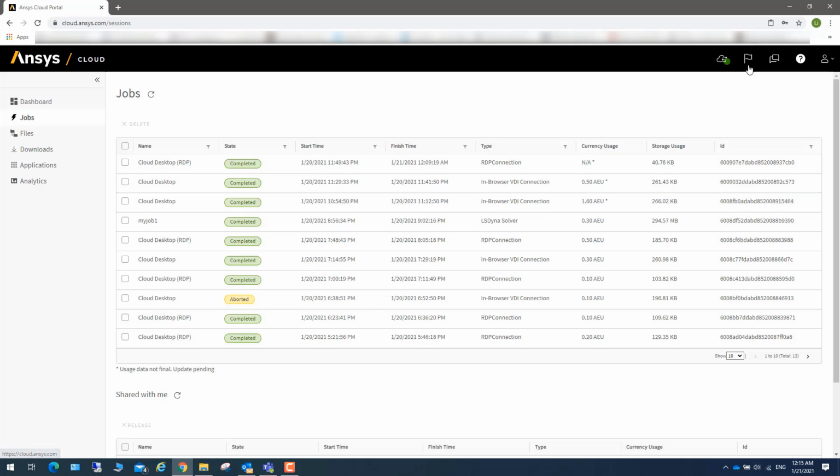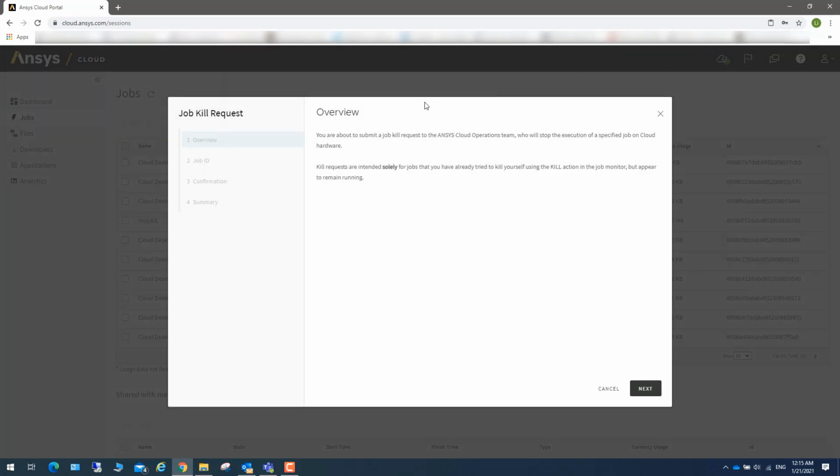It's called Submit Job Kill Request. If you click on it, you can submit the job kill request to the Ansys Cloud Operation Team, who will stop the execution of the job on the cloud hardware. So this way allows you to kill the job when you have difficulties.